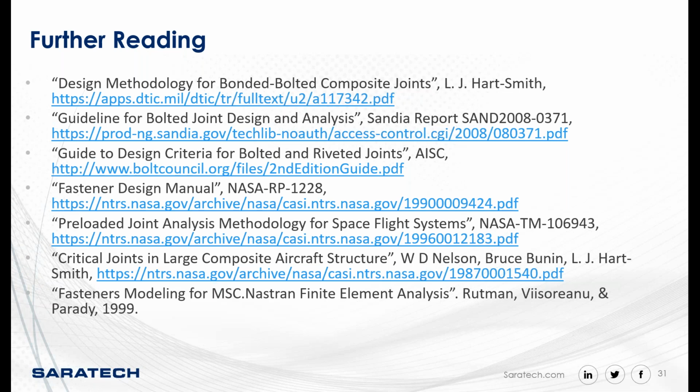So even if I don't anticipate doing a nonlinear analysis, I think it's a good idea just to use beams in case at some point I decide to run something nonlinear. My beams are already in there, and I don't have to worry about changing them, or forget to change them. And I really don't know of any disadvantage to using a beam over a bar. Computationally, I don't think it's any harder.